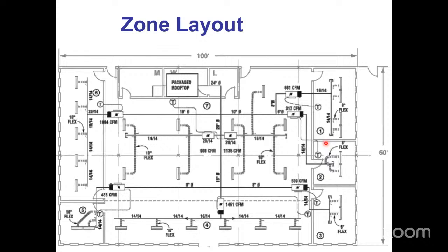Now, this gives an example of a very small system. VAV is usually much bigger than this, but just to give you an idea, there's 1, 2, 3, 4, 5, 6, 7, 8 zones in this case. I know I just said, oh, you got to have at least 9 minimum. In this case, this zone over here on the top, on this side of the equation, is butted up against a manufacturing facility. So it's not really an exterior wall. So it's really just an extension of the core. So this area is basically the same thermal needs as this area is.